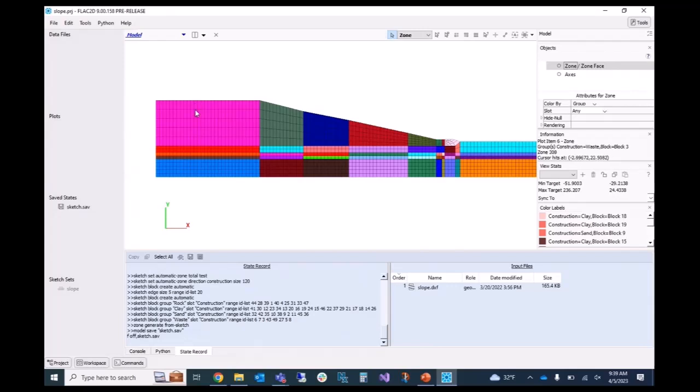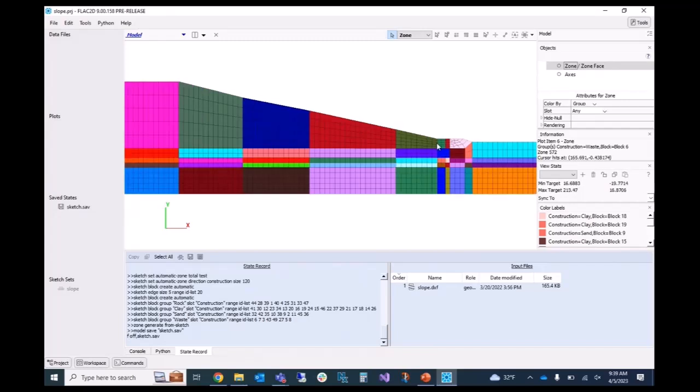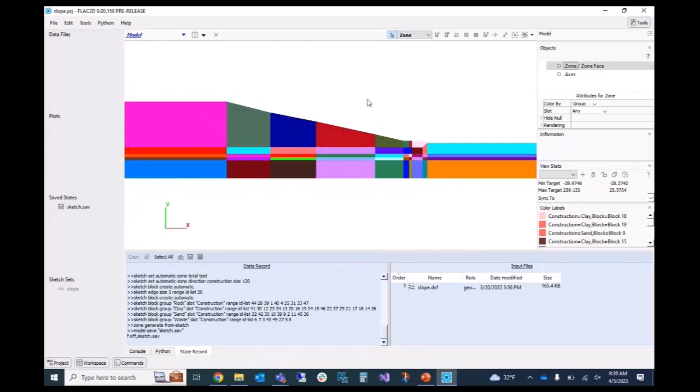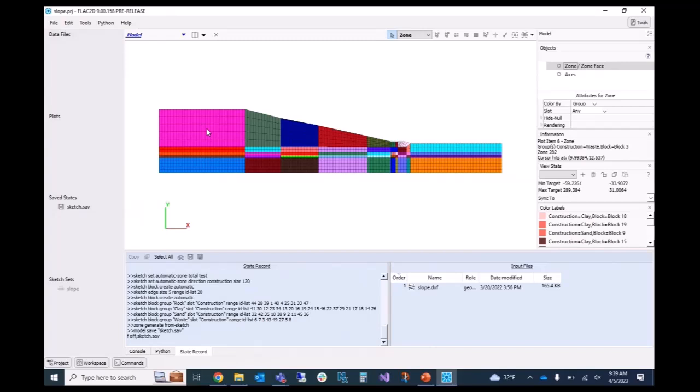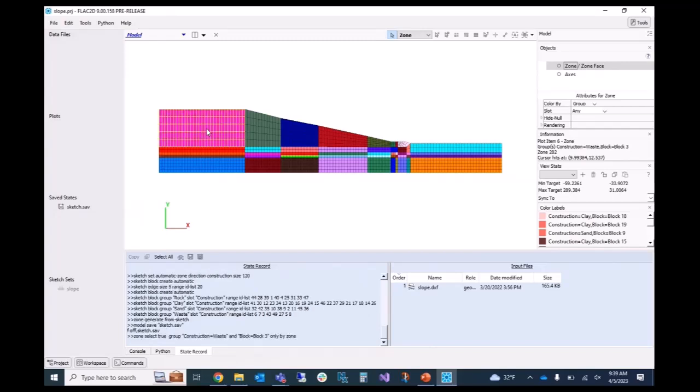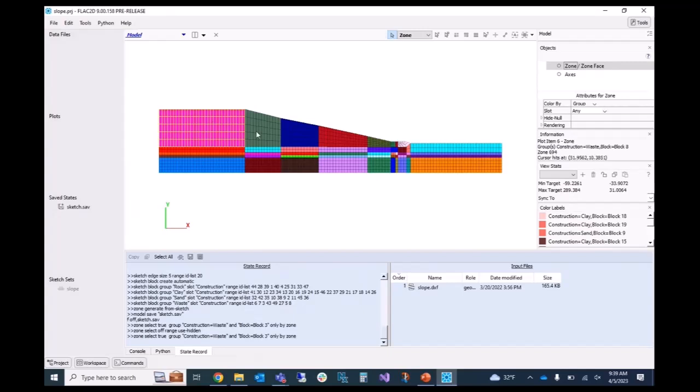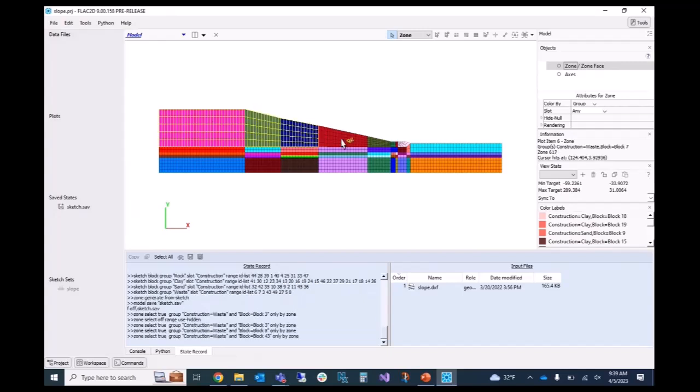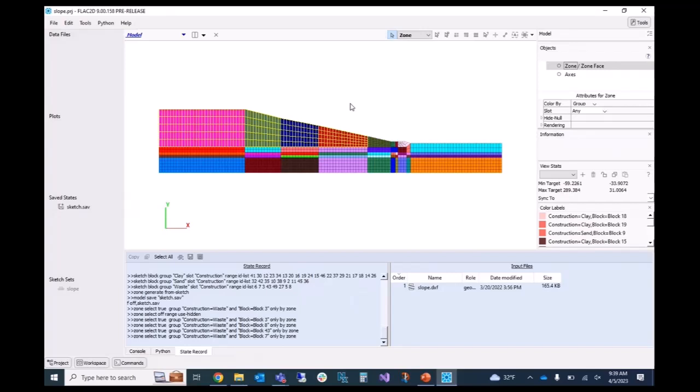Like if I wanted a true structured mesh and said, okay, give me 10 zones here, I'm going to end up with 10 zones down here, and they're going to be tiny little skinny flat zones, right? So what I can do is just densify some of them and not all of them. So if I click on the first one, the pink one, mine's pink, yours might be different. If I click on these top left 4 blocks here, so I'm clicking on the 4 top left blocks because I want them to have more zones in the Y direction.